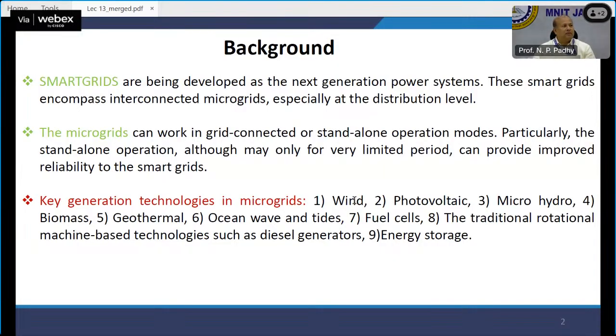It's not at the megawatt level, but maybe 2 kilowatt, 3 kilowatt, 5 kilowatt, 10 kilowatt, 50 kilowatt. Plants can operate with that. Water keeps falling, you put in a small motor and it will generate power and electrify the whole village. These are known as micro hydropower. So you may go to an area which is completely isolated and have a grid where not only PV, but micro hydro plants are also part of the microgrid, which caters to the whole local load.